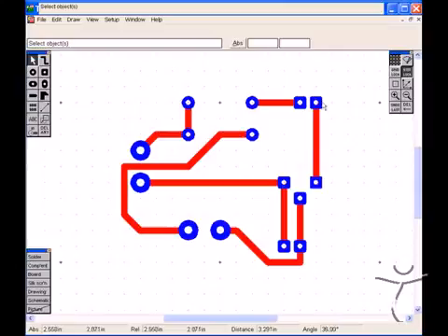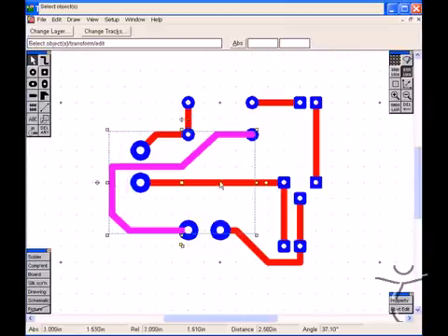It's always important to have a look at the layout in this particular package, because you're going to engrave the circuit board, and there's some locations where the tracks could get very close, so there could be an error here. So what we can do is we can actually select that particular pad and track and just drag that out a fraction, and that takes that out a bit, the location.